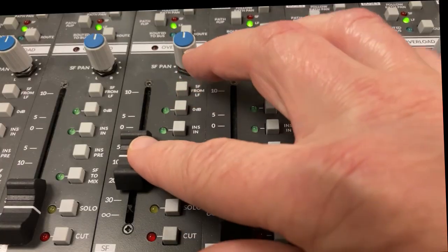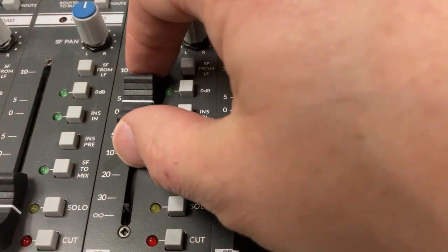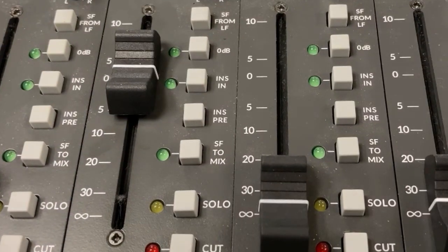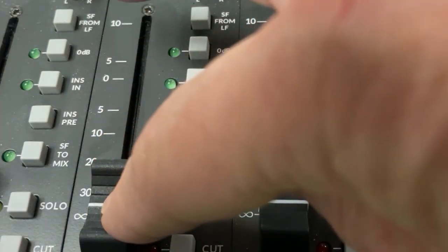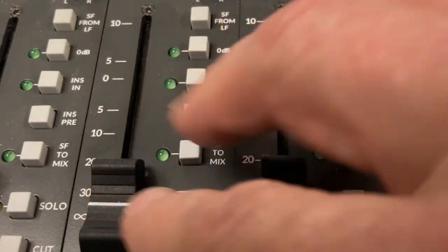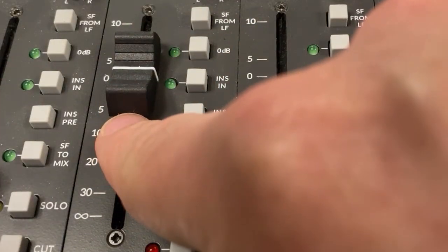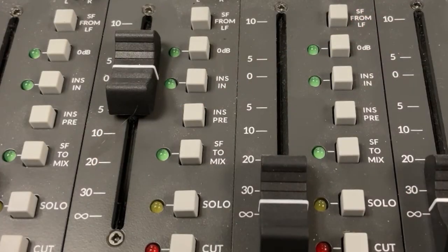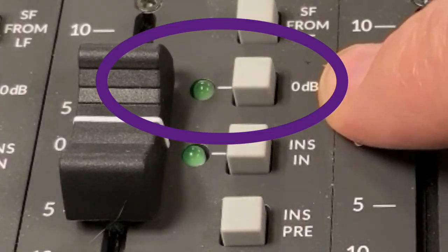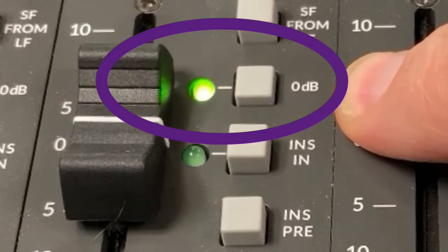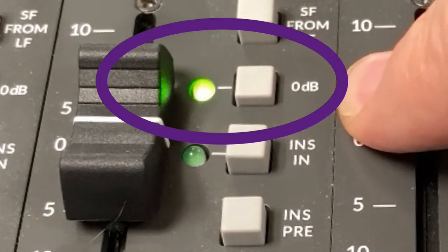So if I take this and I turn this up to 0, a fader electronically is something called a variable resistor. At 0, it is at 0 resistance. So it's not blocking the signal at all. If it's down all the way, it's at infinite resistance. So it's blocking the signal entirely. It's not letting anything through. So on the basic level, we're going to just take this and put this up at 0. There's also this button that says 0 dB here, and I consider this not to be a good idea.